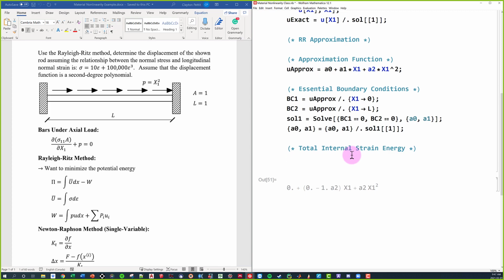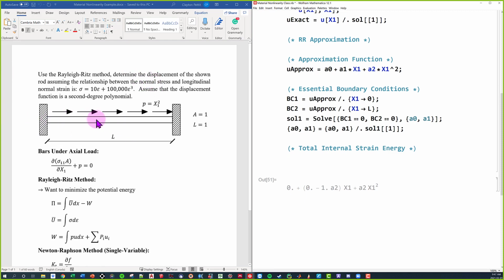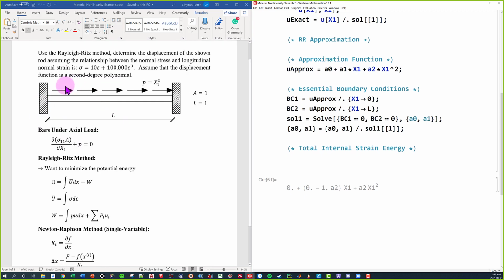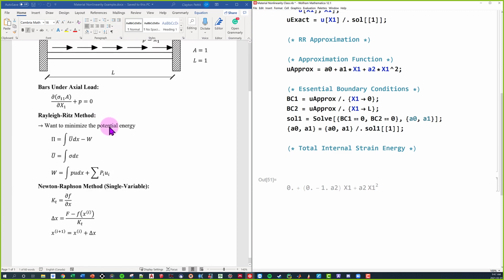So one of the things here is this is a bar element, so the only degree of freedom is axial. It doesn't rotate. Does that make sense? All right, perfect. As long as things are making sense in the end, yes. So if this was a beam, then yes, we would definitely throw in those rotation ones. But since this is a bar, we're only concerned with the axial direction.